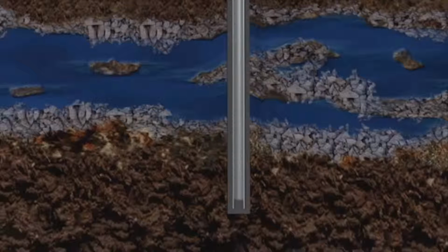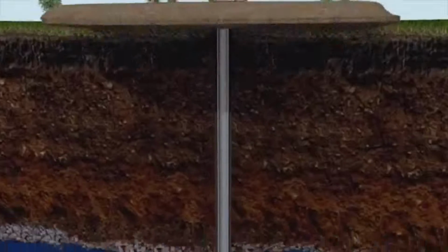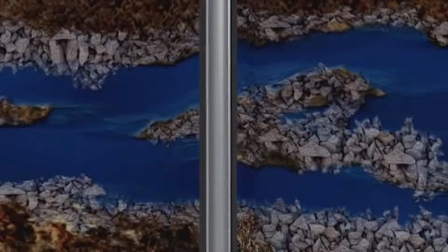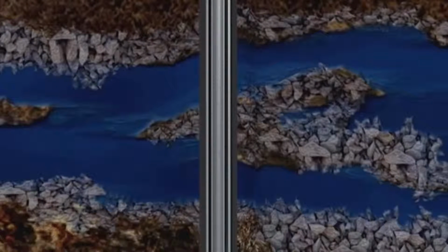When it reaches the bottom, it is pumped back up between the casing and the borehole wall, creating an impermeable additional protective barrier between the well bore and any freshwater sources. In some cases, depending on the geology of the area and the depth of the well, additional casing sections may be run and, like surface casing, are then cemented in place to ensure no movement of fluids or gas between those layers and the groundwater sources.